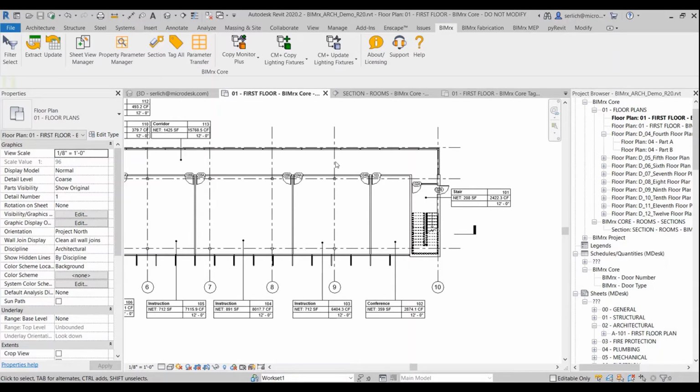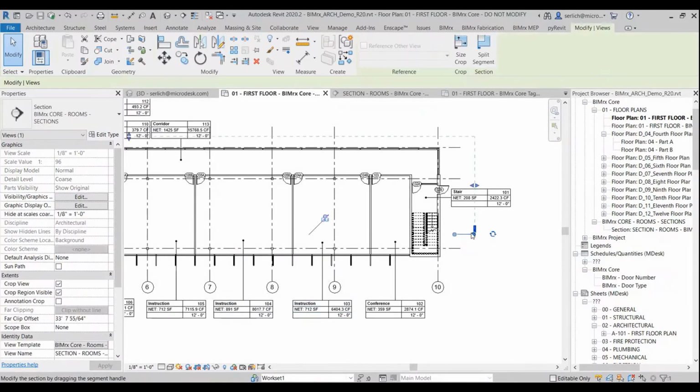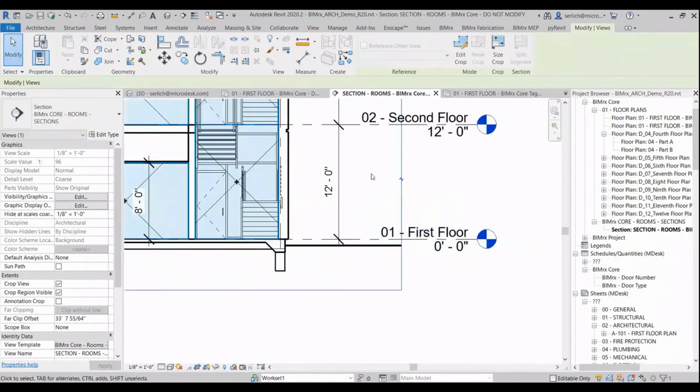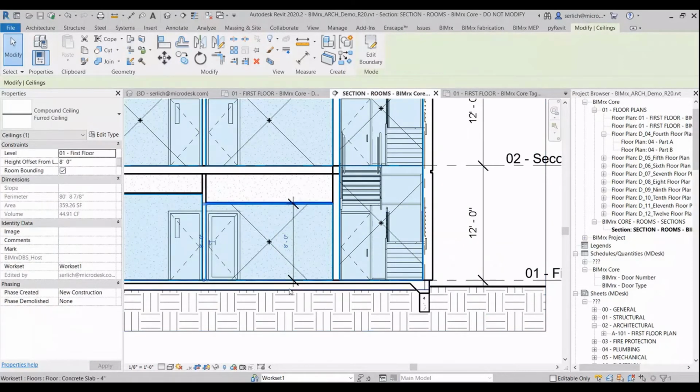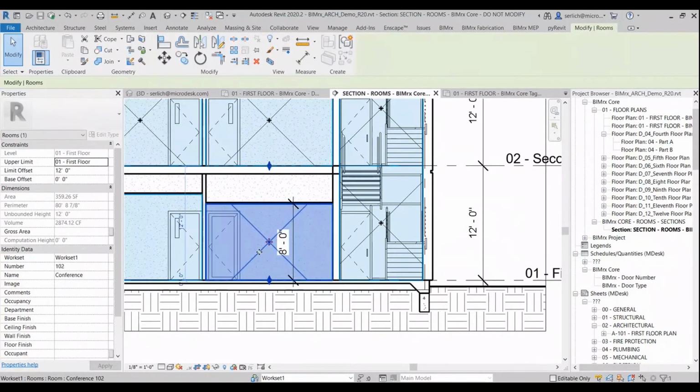So you can see here that I have all of my rooms tagged with the room height up here. And I've specified all my room heights to be my floor-to-floor heights here. But the issue is that my ceilings actually cause my room heights to vary. And Revit isn't capable of picking up that information easily. It can pick up the volume accurately and the area accurately, but it's not updating my ceiling height.